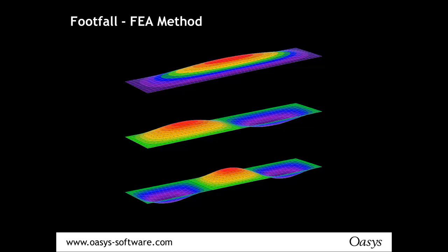Now, first thing you need to do is find out the various vibration modes, and you need to find sufficient vibration modes up to a cutoff point. Now, the cutoff point in the frequencies depends on design guides, but for a resonant analysis, you're looking at say up to about 12 to 15 hertz, depending on the guides and so on. Transient analysis tends to be twice the fundamental frequency.